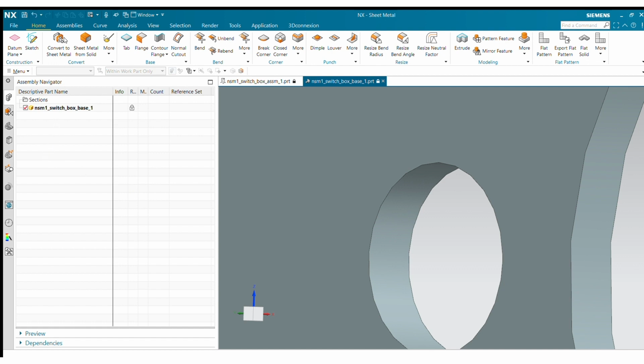So I have visualization preferences opened up, and I want to go to my performance category, and here I have accuracy set. So this is a quick way to increase your accuracy, or if you want more specific settings to update, you can go into the advanced section, change your resolution here, and you can change your facet scale.